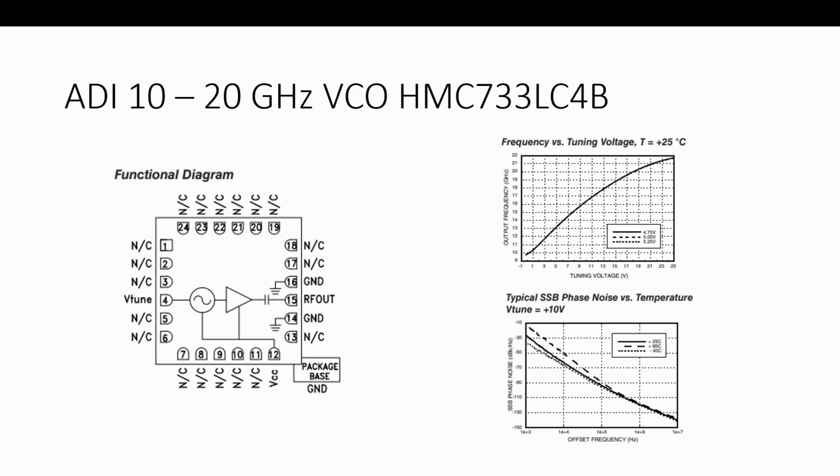We saw how we can look at its frequency versus time or phase versus time. So if that phase is modulating versus time, so if I had phase that was modulating at 10 kilohertz, so 10 kilohertz minus 70 dBc per hertz. If I took that slice with a tight filter, 1 hertz wide, and I looked at the output of the phase detector, I would see phase going back and forth sinusoidally roughly at a 10 kilohertz rate. So that's the phase modulation.